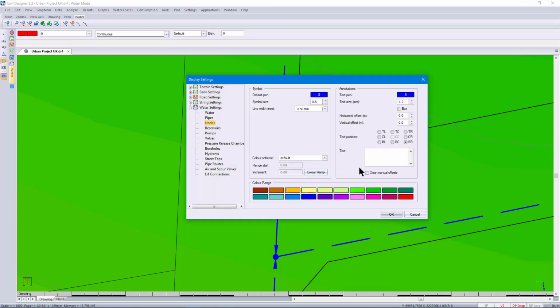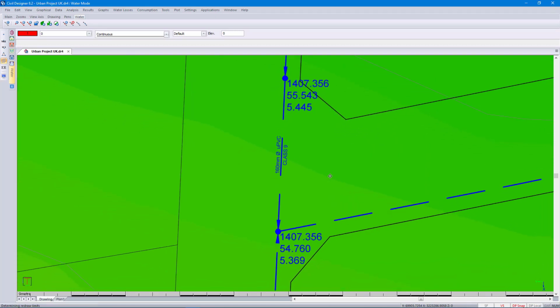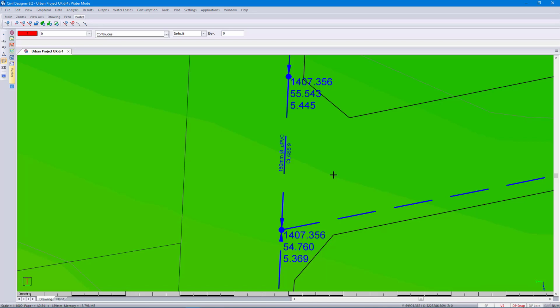For the nodes, we can now choose the pressure in head in meters, we can also choose the residual head in meters, and we can choose the pressure in bar. So there you'll see that you've got your pressure, which is your head in meters, plus the level above mean sea level. Then we have the normal residual head in meters and your pressure in bar.